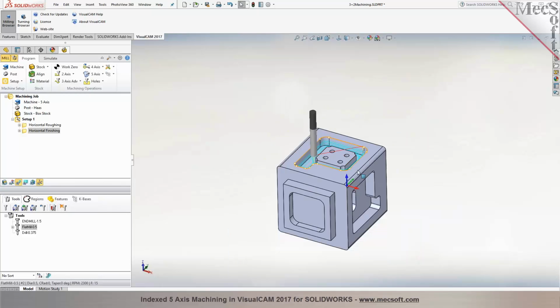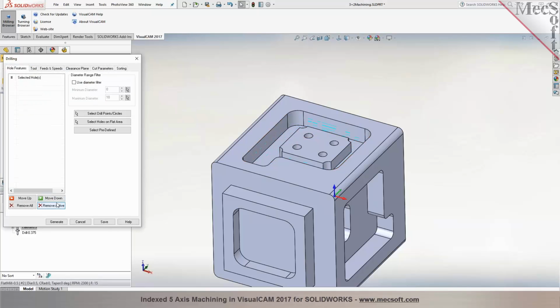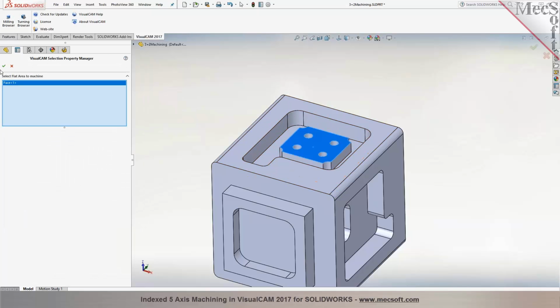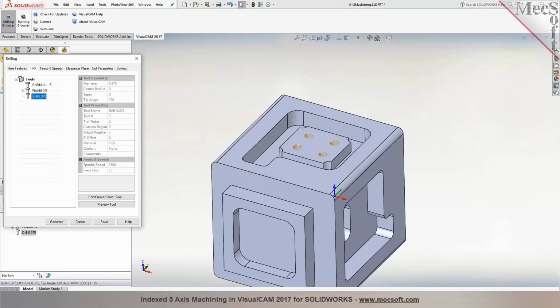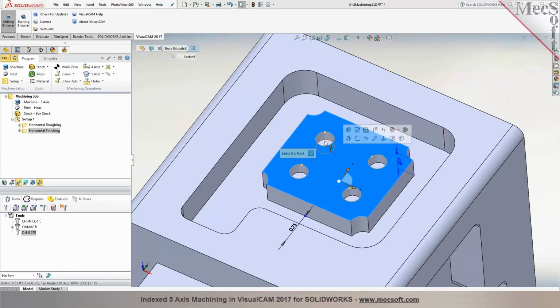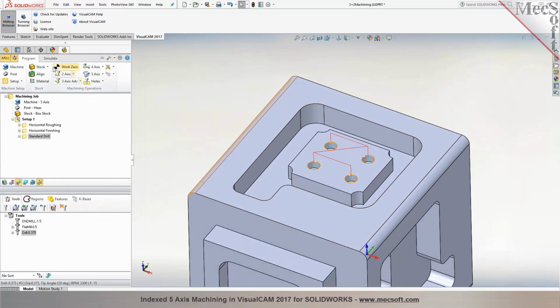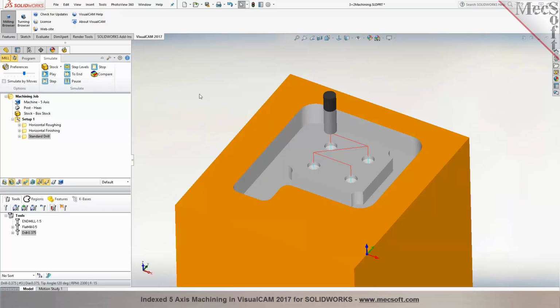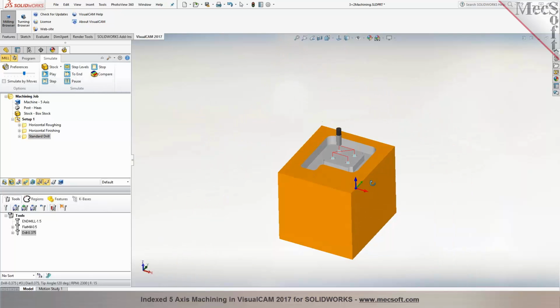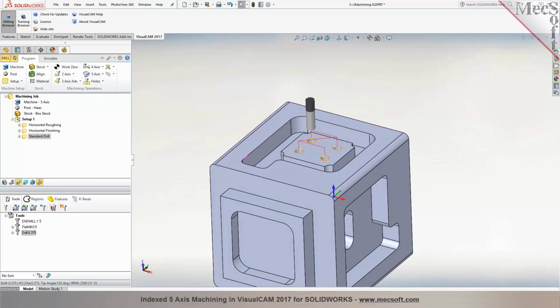Now once you're through programming this top face in here, let me go ahead and just add a drilling too. We'll just do a drilling, and we'll select holes on this particular face. We'll go grab a tool for it, and then we can specify a depth, so you can measure or pick the depth from the face. And I remember you told me that depending on what kind of strategy for drilling, the software will create some of those canned cycles, I think it's G78, G81, G83, yes, it creates canned cycles.